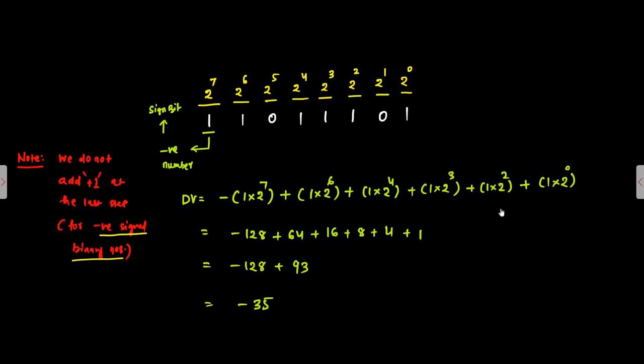For 1's complement, it is a bit easy to identify bit patterns. Just by looking at them we can say, okay, this is the 1's complement of this. But for 2's complement it is a bit difficult because we first have to take the 1's complement of that binary number, then add a 1 to the LSB, and the resultant is the 2's complement.